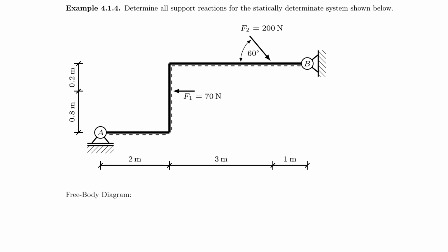Now, I'm not going to solve this problem entirely for you. I'm just going to give you some hints here, and I want to talk about the actual support reactions. Of course, you understand that here on the left you have the roller, which means you have RAY acting in this direction, and then on the right side you have RBY, and you also have RBX in this case. You can also call them vertical or horizontal, it doesn't matter. RBY and RBX.